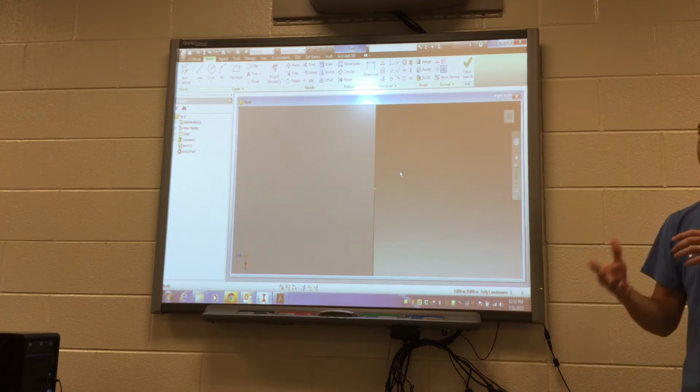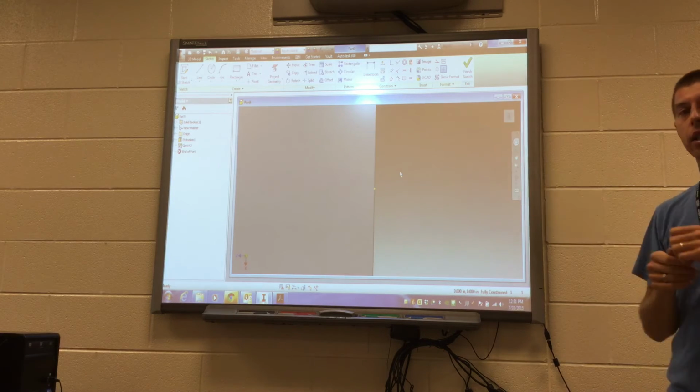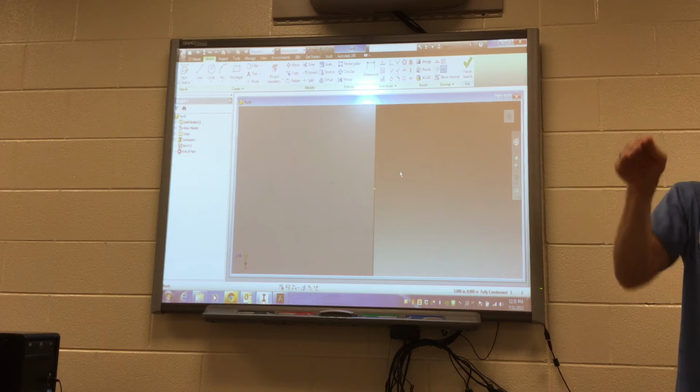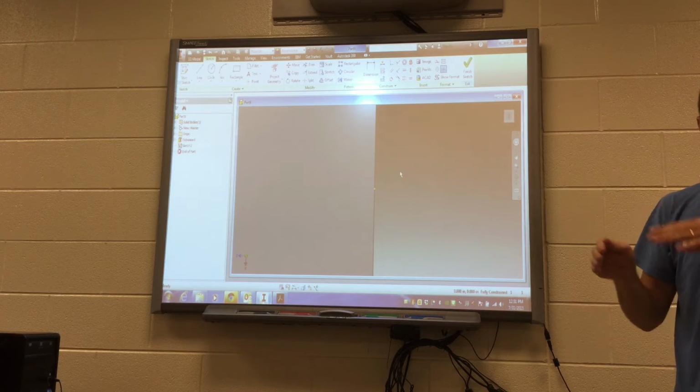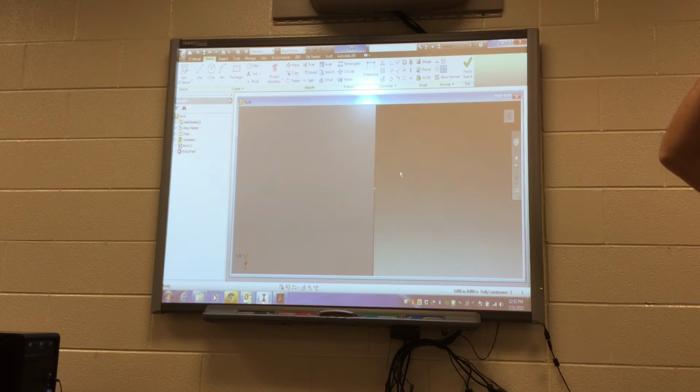When you start a second sketch, I think it's a lot easier because all you need to do is hit Create a Sketch, and then literally go through and say which surface do I want to start that sketch on, and click on it. So there's no planes that you got to think about whether they're front, top, right, whatever. It's what surface am I going to add something to, and then I click on that, and you can start from there. So really, I think after the first one's done, it gets a little easier.